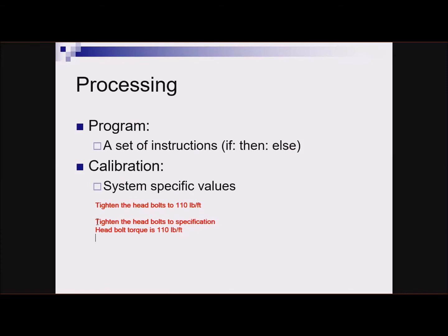In the second one, you can have the same process, the same program, if you will, the same steps, but you can change the torque setting and reuse the process, reuse the instructions for different vehicles that have different size head bolts, let's say. Same exact process, different number. Now, I know that doesn't seem to make a whole lot of sense when it comes to a computer, but I think I can show you in a little demonstration in a few minutes how that would work in real life.